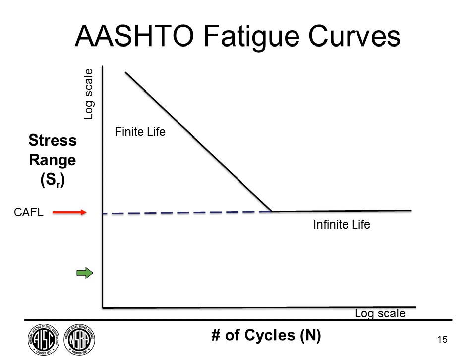And I can tell you, when we do fatigue tests here in the laboratory, they're all generally simple span girders. And the students always go out and look at the bottom flange. That's the tension flange. And I tell them, look at the top compression flange. And they say, why? Because of the tension residual stresses. And sure enough, we crack compression flanges. Why is that? Because of the high tensile residual stresses. They're actually cycling in tension due to the residuals.